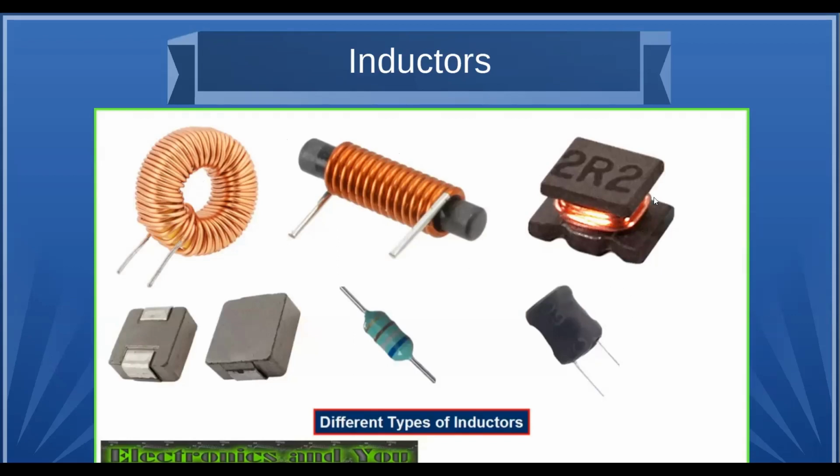There's some other forms here where they're wound turns around this little insulated thing. These are surface mount inductors where there's a coil inside of that. These are not to scale. This thing would be maybe 1/8 of an inch square. This is a small inline inductor. Sometimes we call them chokes. It looks like a resistor, but there's actually a little coil in there. This is just another form.